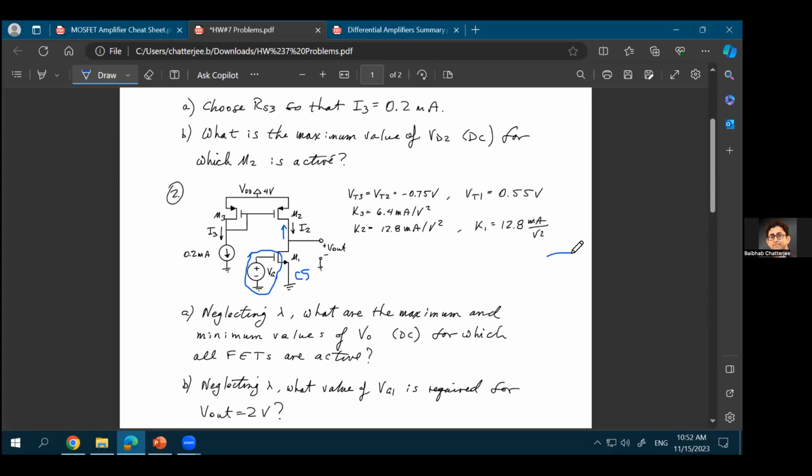So it's nothing different from this structure that you had learned before, that you have a common source amplifier. You apply your input at the gate, you take your output from the drain, and at the drain side, looking up, you'll see a resistance connected, right? That's the basic common source amplifier you have learned. This is nothing different from that. It's the exact same circuit.